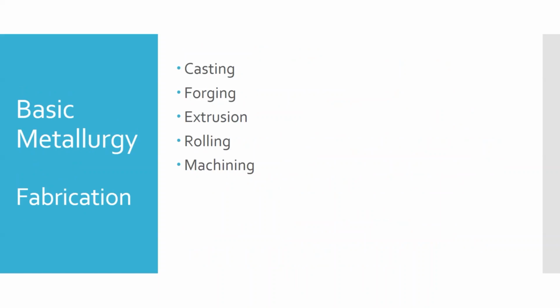Rolled parts tend to have a little bit smoother surfaces, or polished or machined parts can sometimes be mirror smooth. And that's going to interact differently with the different testing materials and testing chemicals than something with a rough surface. So keep that in mind when you're doing different techniques and trying to decide what's appropriate and what kind of indications you are seeing.